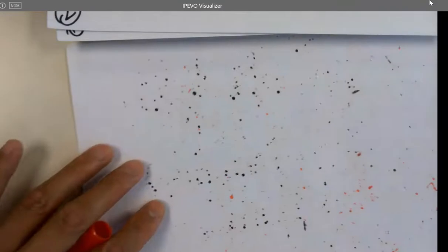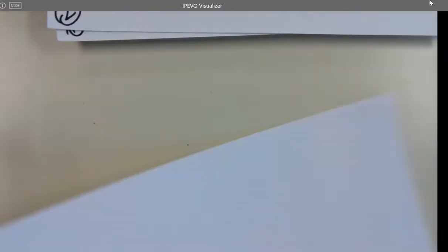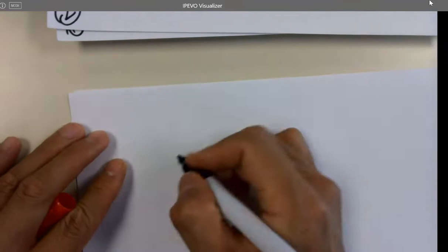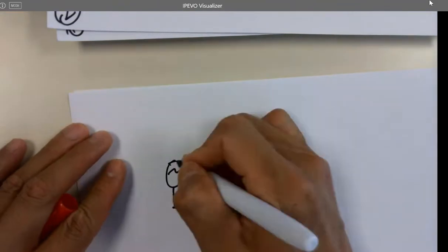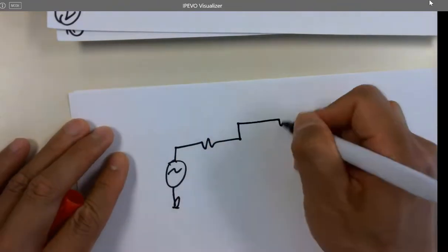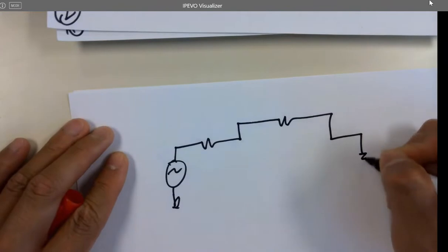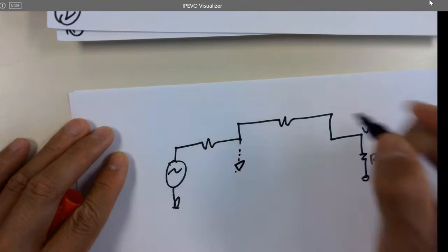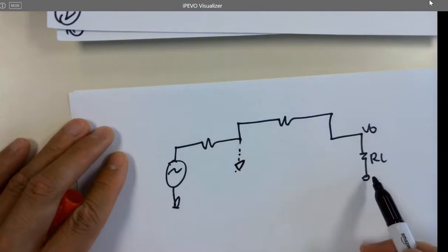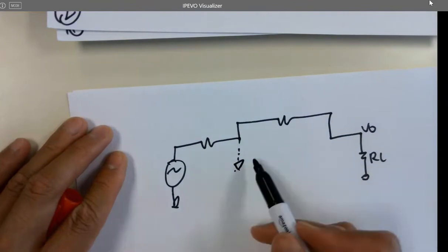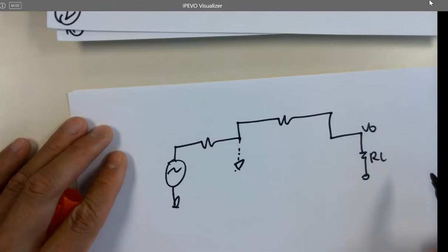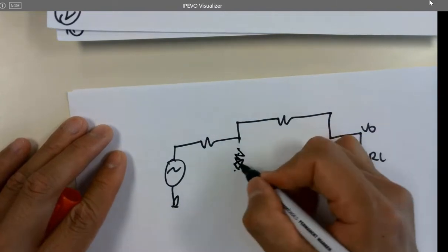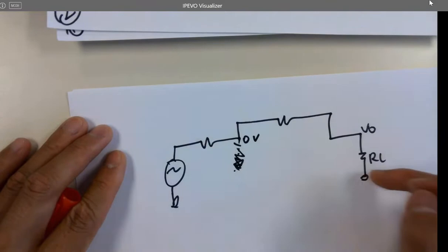So why the OpAmp? When we put the OpAmp there, it works. No, it's not 0, okay? Don't short it, because they're not the same point. Are they? They're not. You cannot short it. It's virtually grounded. It's just 0 volts, but it's not grounded.